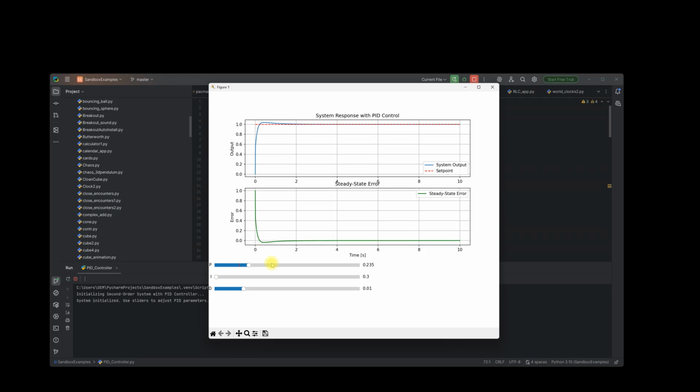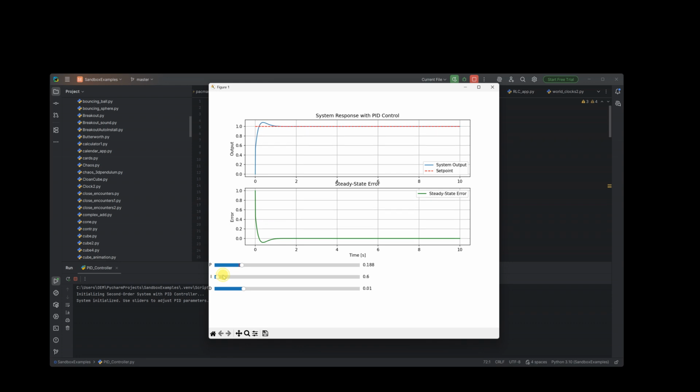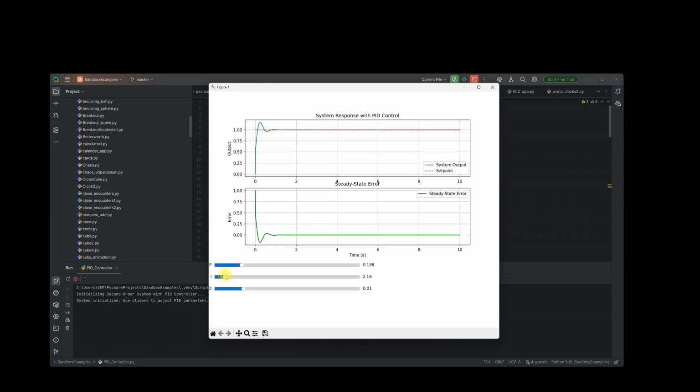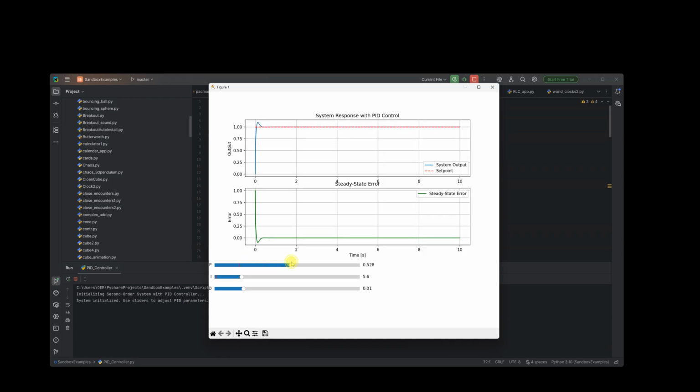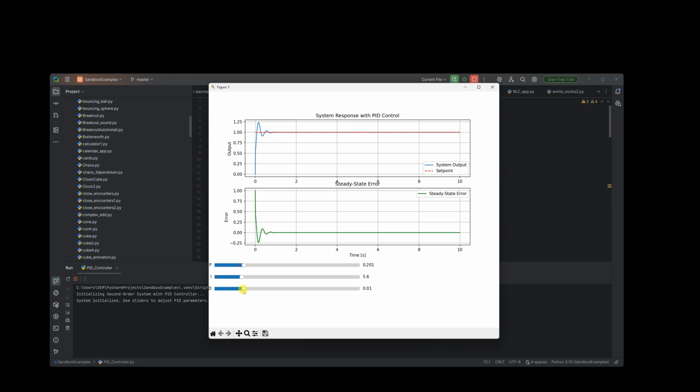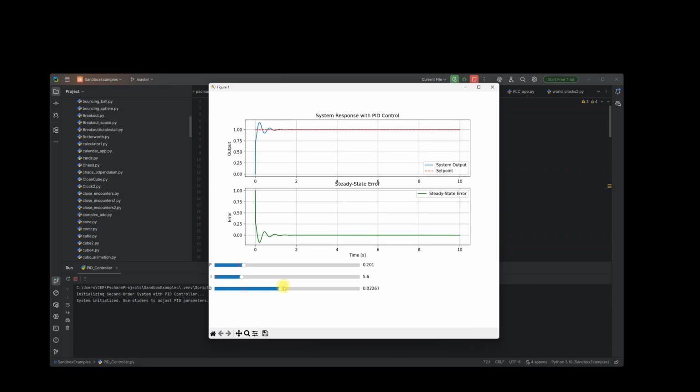If I increase the proportional gain, it gets quite nice actually. But if I want to put in another, second integrator, two integrators is always better than one. Notice how I get the ringing and it goes down. If I introduce derivative action, which dampens it, then I should run into the structural resonance eventually. Oh, there it goes.